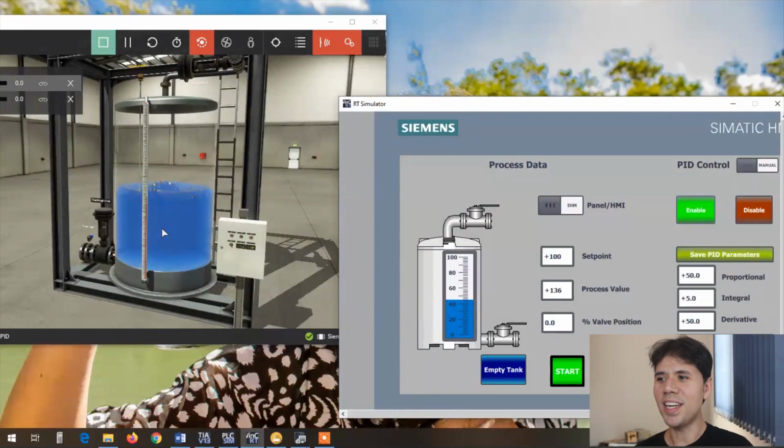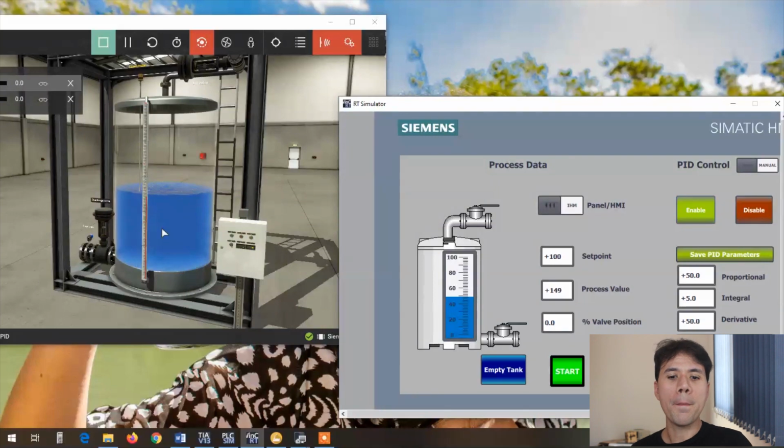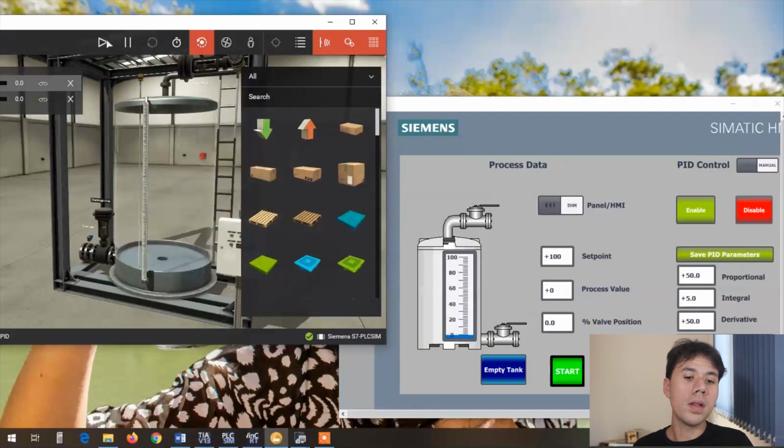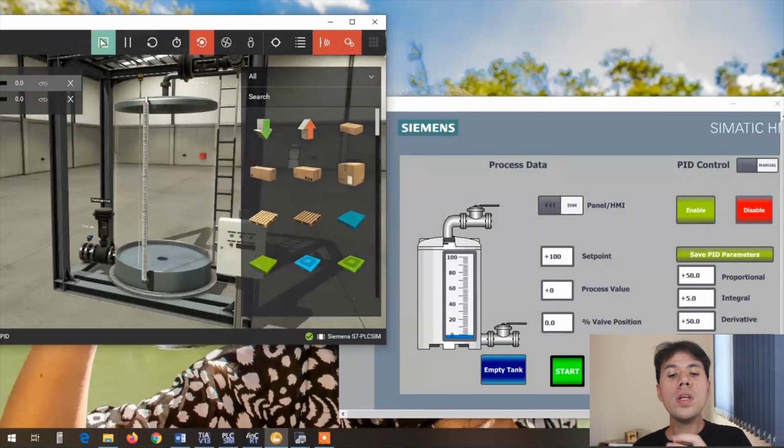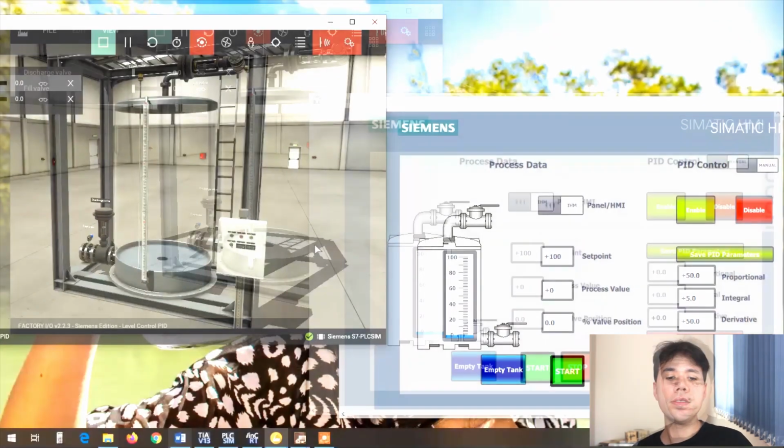Okay, I think we have seen enough. You see, now the controller senses that the PV is coming too fast and tries to slow it down by shutting down the output. These sudden changes in the output created oscillations in the water, thus making the water measurements oscillate as well. So we have to be really careful when adjusting the derivative action.